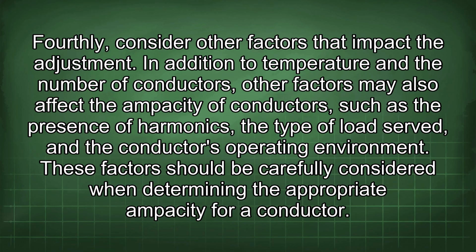In addition to temperature and the number of conductors, other factors may also affect the ampacity of conductors, such as the presence of harmonics, the type of load served, and the conductor's operating environment. These factors should be carefully considered when determining the appropriate ampacity for a conductor.